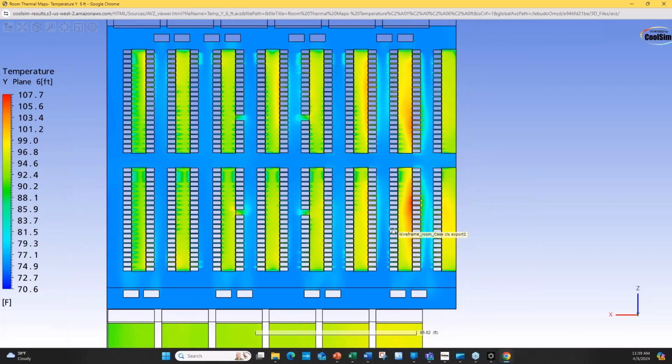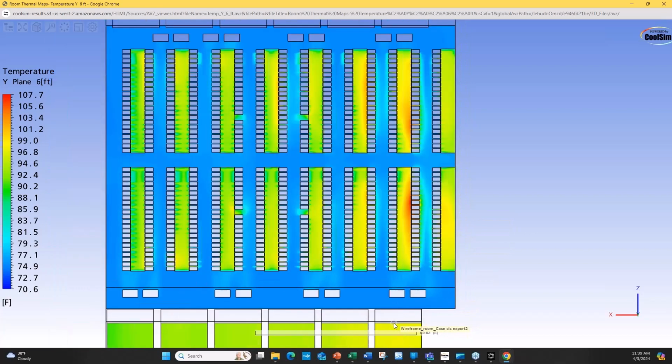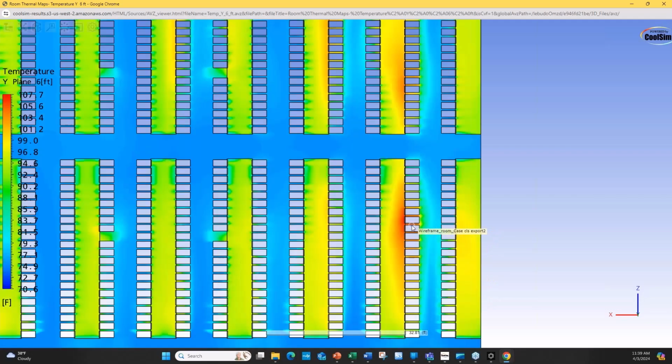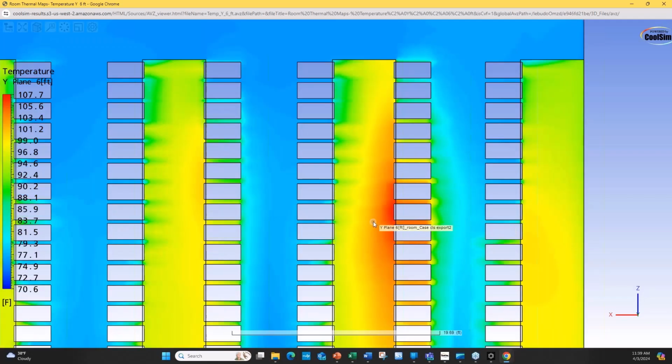And as a result, pressure over here in certain parts of the geometry, you can see the air handlers here on both sides. So this is kind of a corner over here. The air is going to come down, and by the time it gets here, it's leaked out into the hot aisle already. There's no air left for this region. You get a pressure differential over here where the pressure in the hot aisle is higher than it is in the cold aisle, and it comes squirting right through.